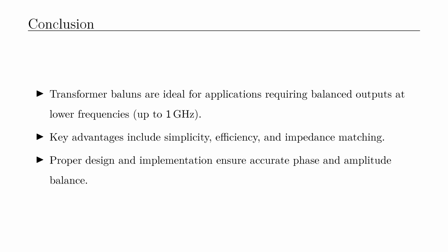In conclusion, transformer baluns are highly suitable for applications that require balanced outputs at lower frequencies, up to 1 GHz. Their simplicity, efficiency, and ability to achieve precise impedance matching make them indispensable in many radio frequency systems. Proper design ensures accurate phase and amplitude balance for optimal performance.